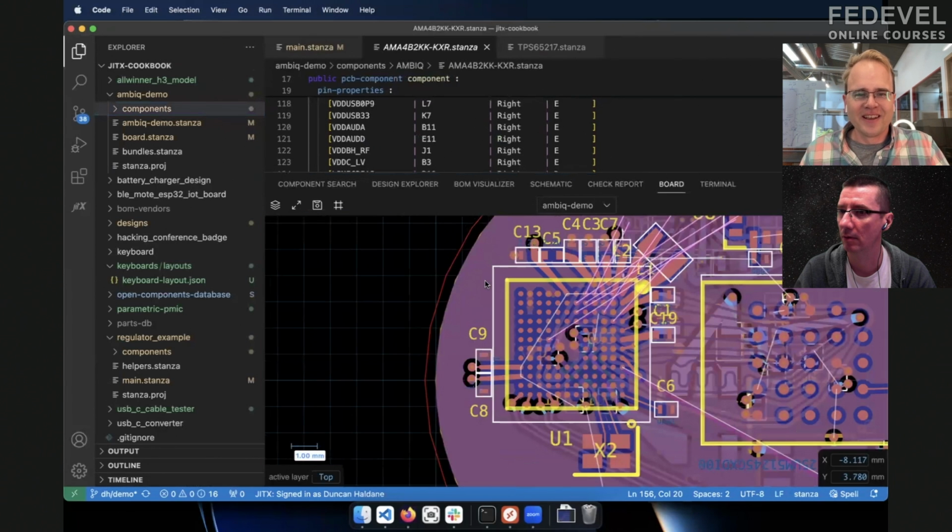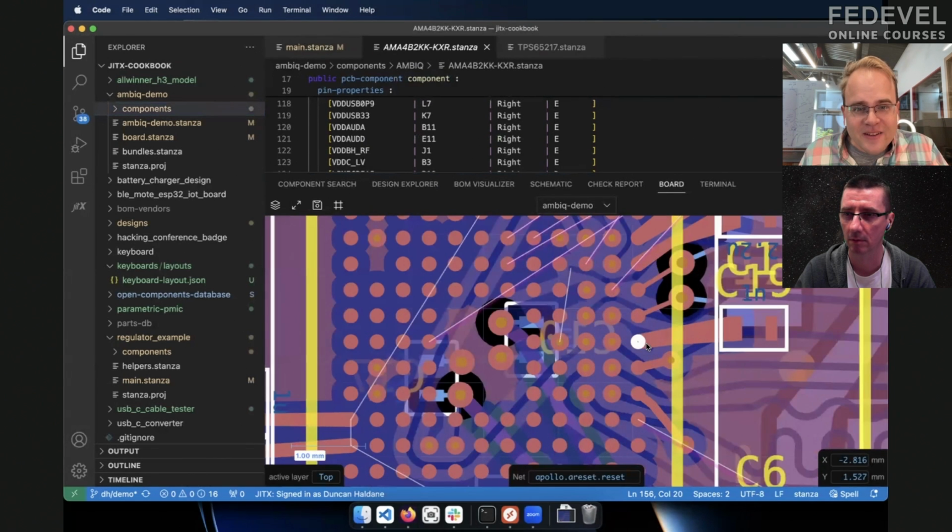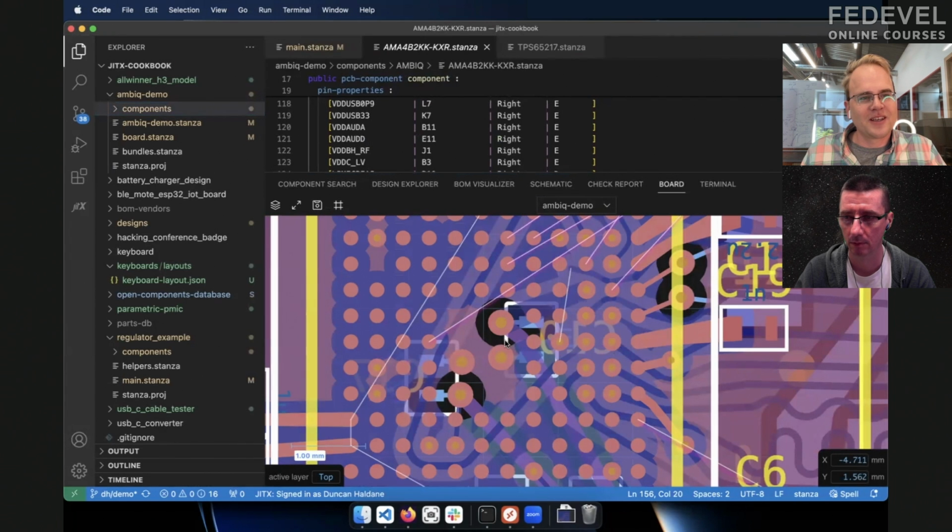People use this because it has really, really efficient megahertz per microamp. So if you want to scale your compute in a battery-intensive application, this is a popular chip. The annoying thing is it's got 5 rows of 0.3 millimeter pitch bumps.